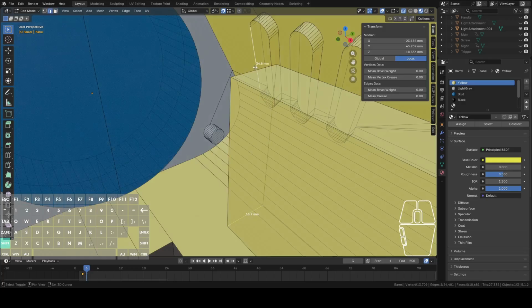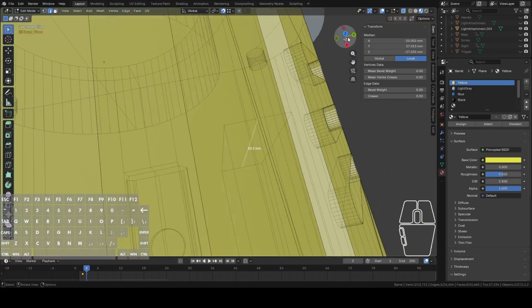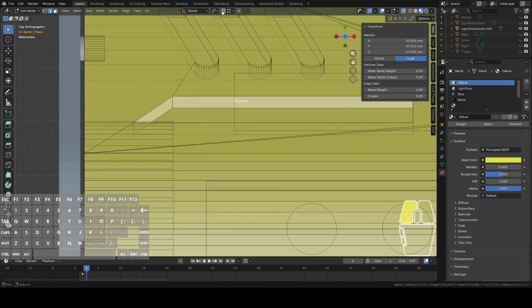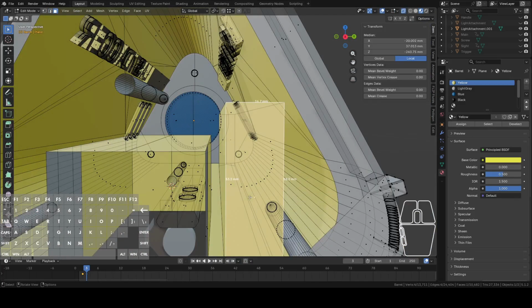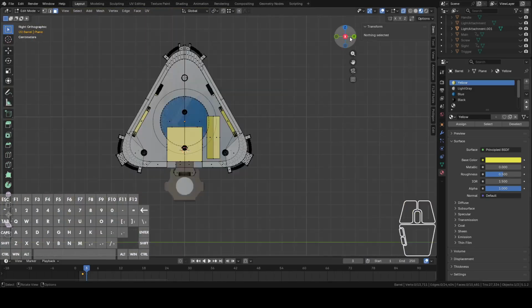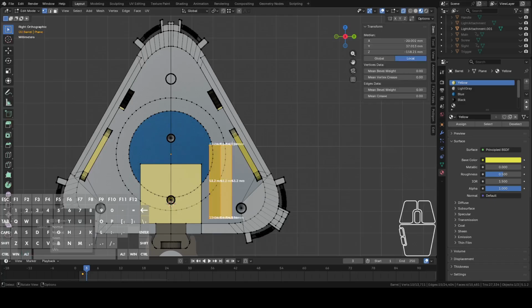And then I'm going to angle it, kind of like we did with the cones, to prevent the need to print support. Maybe I'll do my square trick. I don't think we're going to need to. Let's get snap off. That seems adequate. That'll create some area that we don't need to print in, saving us a bit of filament and time. And we'll mirror this in a moment.